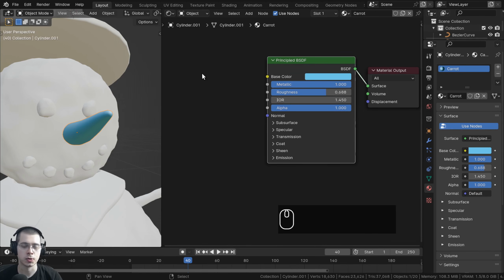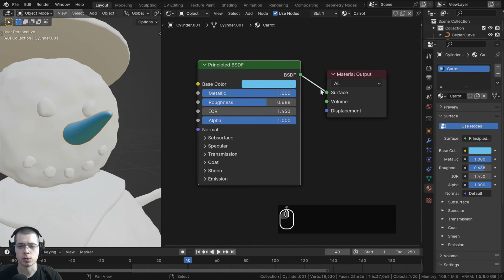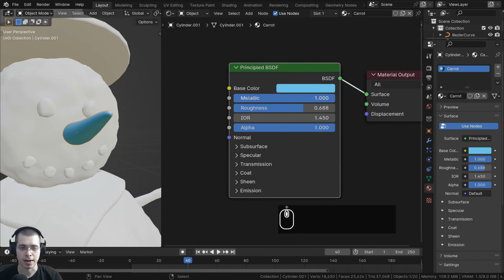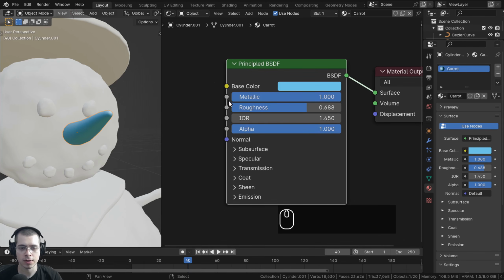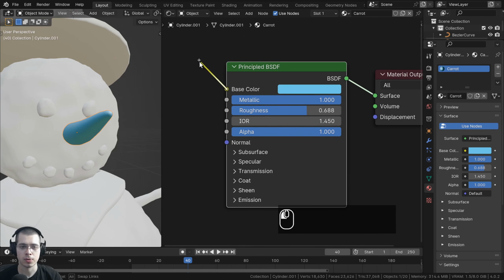If you want to add textures or colors or other data, those are also going to be nodes. Now these wires here are used to connect up the nodes. The wires are basically how all the nodes communicate. And these little circles on all of these nodes are basically the sockets where the wires plug up. If you click and drag on any of these circles, it's going to bring out a wire. And so you can plug the different wires up to each other. Like I could click and drag and then plug this one up here.